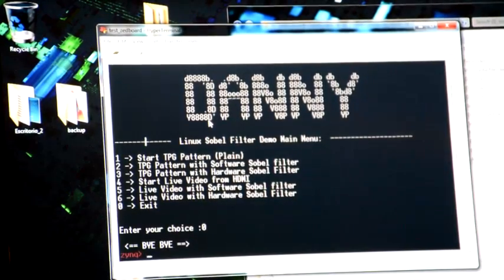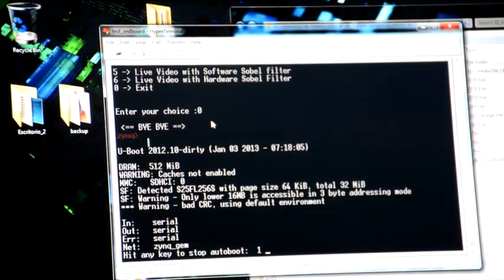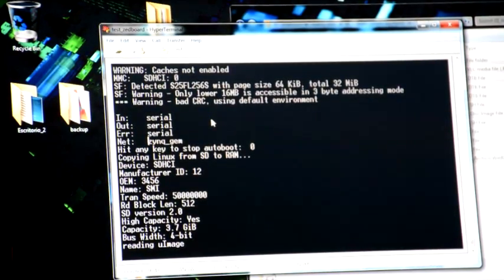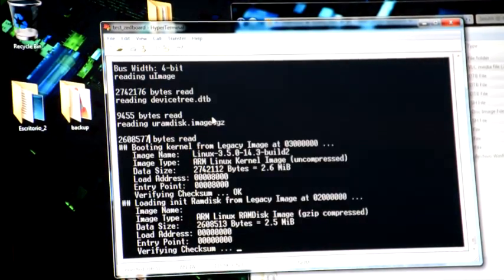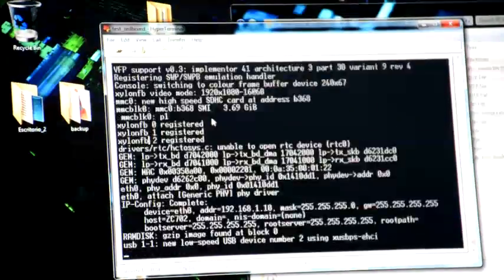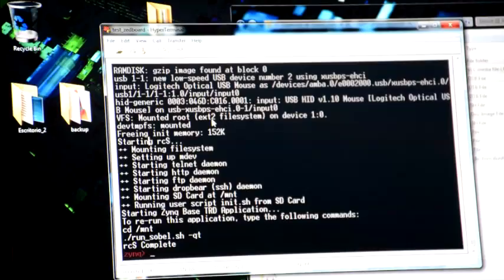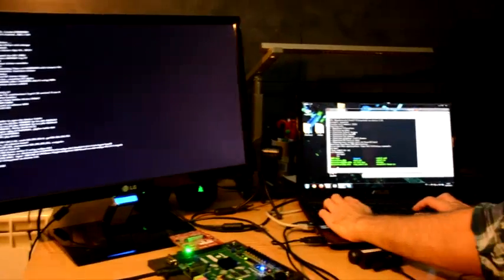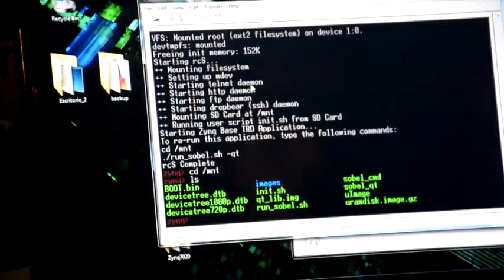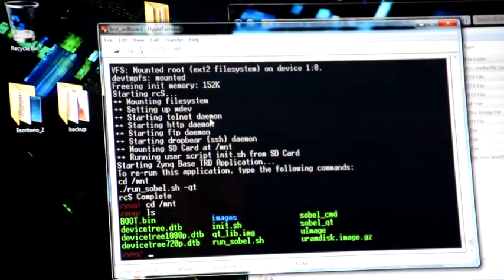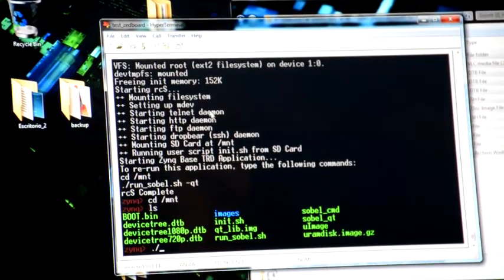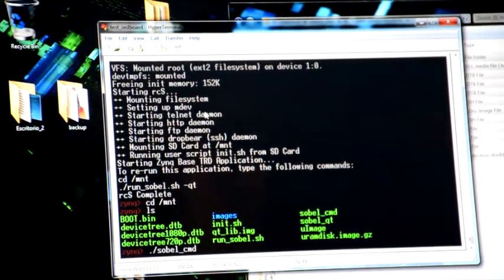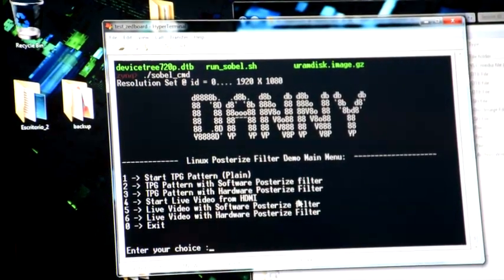This kernel is the normal Linux operating system kernel. Later I will show another one done with PetaLinux, which is a Linux operating system developed by Xilinx. Here we have to start the command center or the graphical user interface. In this case, as you can see, the commands are exactly the same as in Linux. We have cd, for instance, for changing a directory. So we have to go to the main directory to search for the program that we have developed.